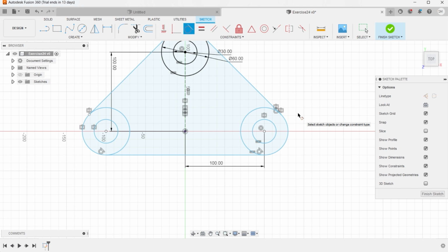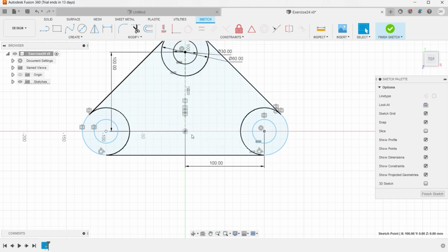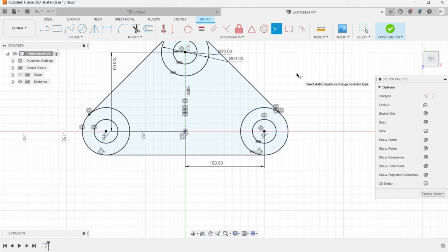We have completed the drawing, but it is not fully defined because the color of the sketch is blue. It needs to be black, definitely. So some other constraints need to be satisfied, right? Three different points are collinear. Select this point, and also this point, and we need to provide the relation of collinearity. Done. So the drawing is complete.